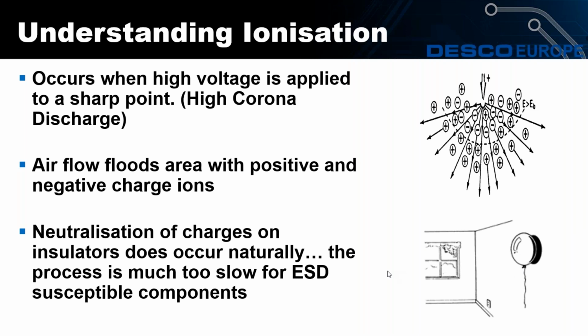But over time, that balloon will fall because neutralization does occur naturally. The charge will disappear naturally over time, but that process of natural neutralization is much too slow for the protection of ESD susceptible components. And for that reason, what we're looking at is ionization in electronics assembly, we have to look at ways that we can neutralize charges on insulators and isolated conductors.